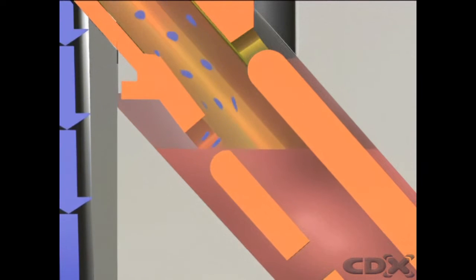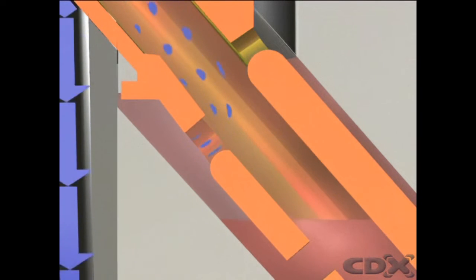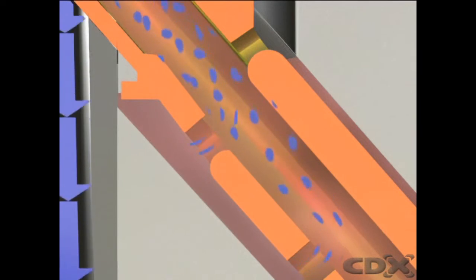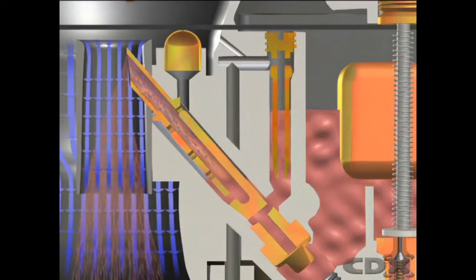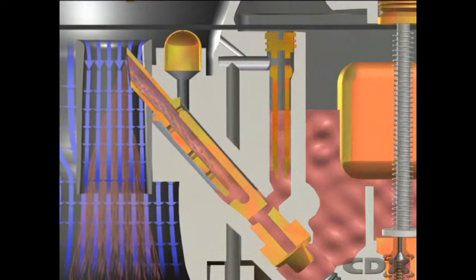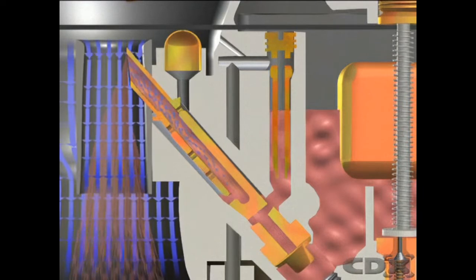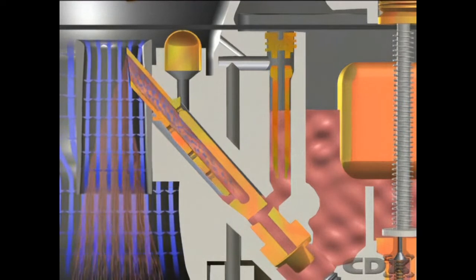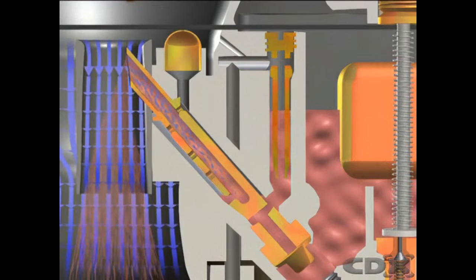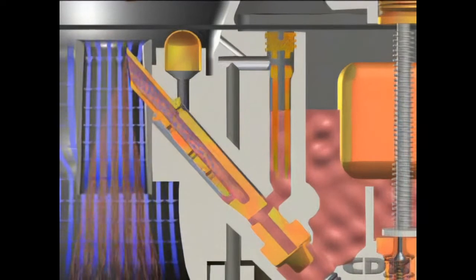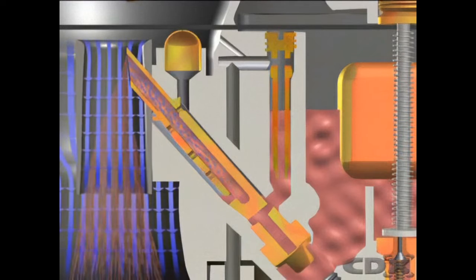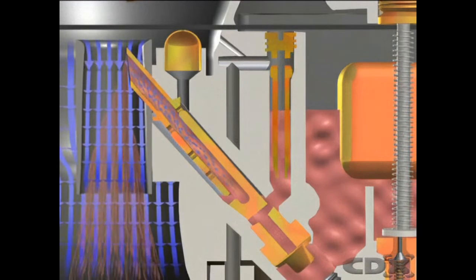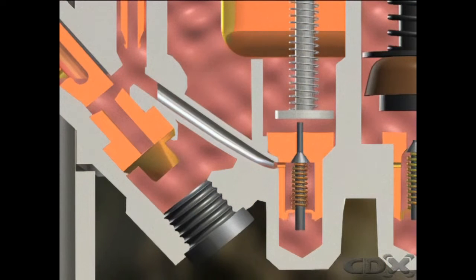Air can now mix with the fuel and stop the mixture becoming too rich. As the throttle opens further, the fuel level falls too, exposing more air holes. More air bleeds in to maintain the correct mixture. The size of the main jet is selected to provide the best mixture for economy under cruising conditions. When the throttle is open wide for maximum power, a richer mixture is required.